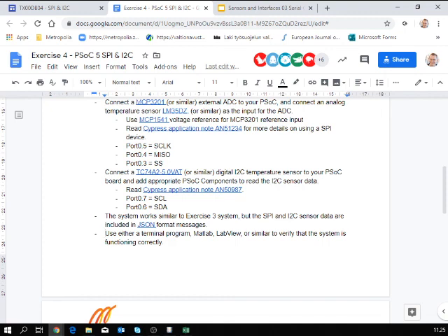You also need those pull-up resistors for the I2C bus, unless, I'm not sure how large the pull-up resistors inside the PSoC are. It might actually work even with those. But if the pull-up resistors are too big, you may end up in trouble that the line does not release fast enough.